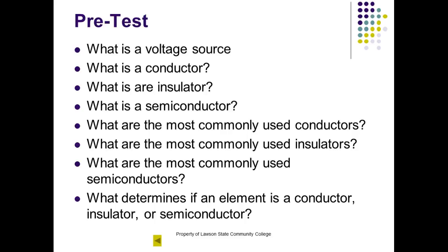And the ground and the neutral wire carry no potential. The neutral wire carries no potential. The ground is not even supposed to carry current, so it doesn't carry a potential. It's not supposed to carry a current. The ground only carries a current when you've got a bad problem. Well, it blows the breaker. It should pop your breaker.